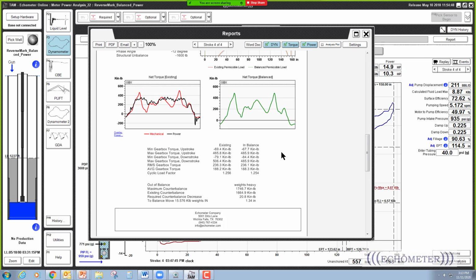One of the problems with VFD is on the outside of the VFD, the power is normal. On the inside of the VFD, between the VFD and the motor, the power has changed. If you measure the power on the outside, then that's more representative of what's really going on that the power company sees. If you go into the inside, then the frequency's changed, and you can't really use it between the VFD and the motor. So I'd say you have to measure it on the outside of the VFD.